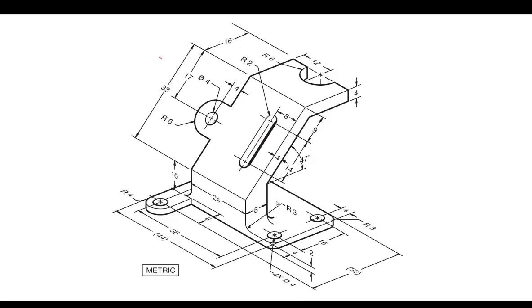I think the next thing you want to do is identify the order of operations and which solid modeling techniques you're going to use. In this one, I believe that we could mostly use extrude tools. There are probably some other ways you can get to do this, but it looks like extrusions will be the main way to go. Now what we see is they're not extruded all in one direction, so there may be multiple extrusions that we could accomplish. And while this could be accomplished in one sketch, I'm going to show you how to do this in several sketches because I think it may be easier for most people to conceptualize.